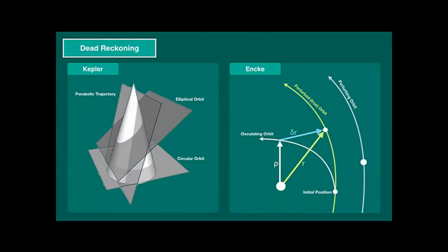Thankfully, there are 2 mathematical models implemented in the Apollo guidance computer. Conic integration, based on the Keplerian orbit model on the left, which assumes one perfectly round gravitational body influencing our flight path, and Encke's integrating method for perturbation, considering multiple bodies with gravitational imbalances. I think this helps to understand why we need a computer on board and can't just fly to the moon